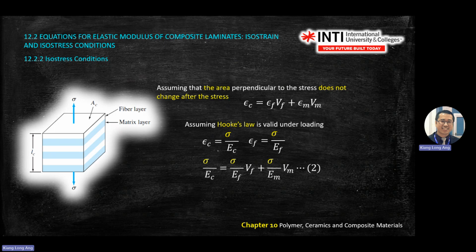Right? So the rest is just, again, use Hooke's law. You convert this equation into stress and Young's modulus. So you convert this one into composite, stress and elongation, Young's modulus. Here same, stress and Young's modulus. Matrix also same, stress and Young's modulus.